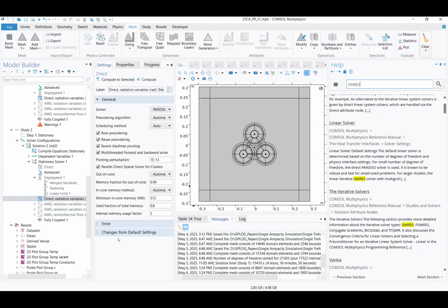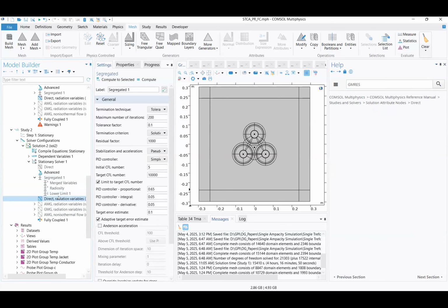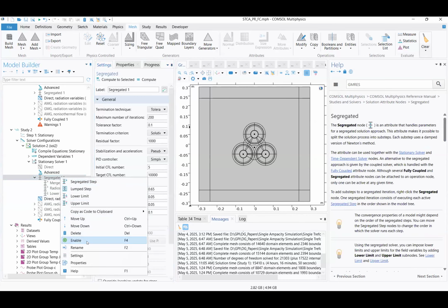It is really good. I have seen these options in nonlinear solver settings. Yeah. FGMRES and these things, but they are not in the general solver settings. For the nonlinear solver settings, these options can be selected. Well, I'm happy they have them because these are the most advanced things. The Krylov subspace, all of them are Krylov subspace. And Krylov subspace is basically multiplying for your best next guess of the inverse of the matrix.